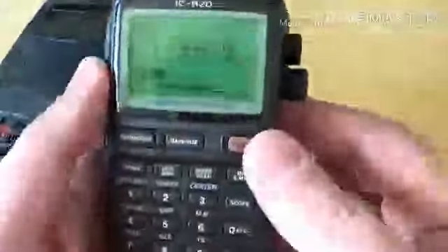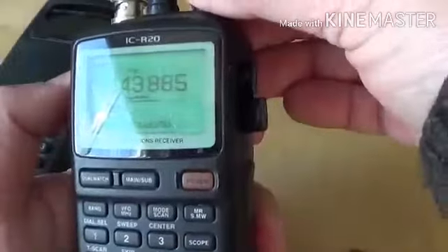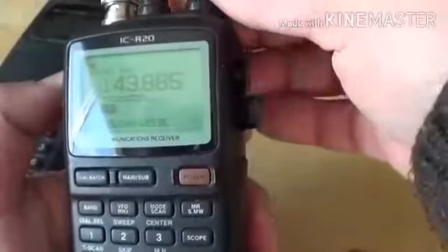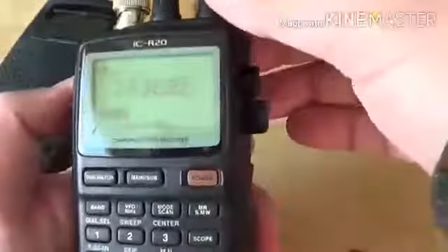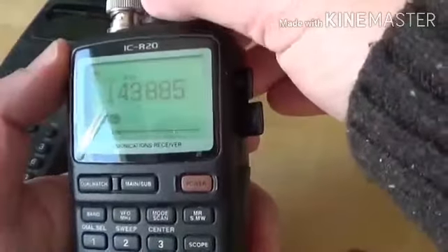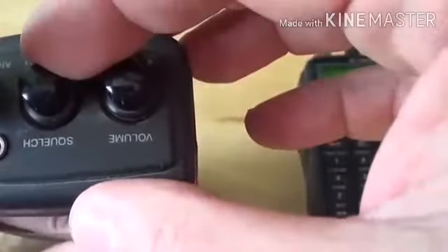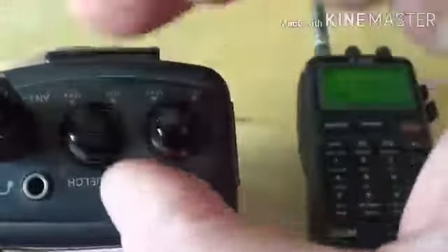The squelch setting is very important. Here in this radio, when I press the squelch button and I want to turn it off or on, it has different levels. You see level 1 to level 9, and of course we've got open. Open means there's no squelch at all. In a more regular scanner that you have every day, you usually have this squelch button on top of the radio, and it's basically a little tuning knob, kind of a variable resistor that you turn.